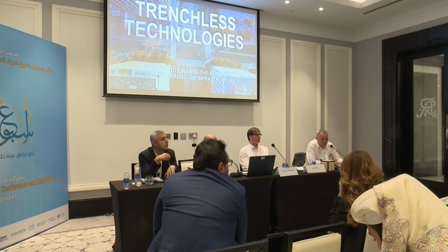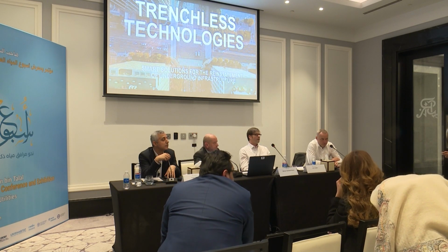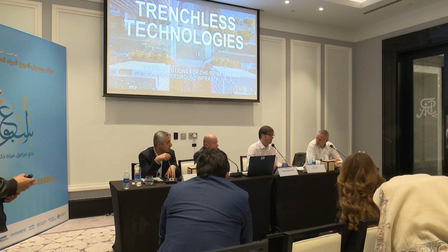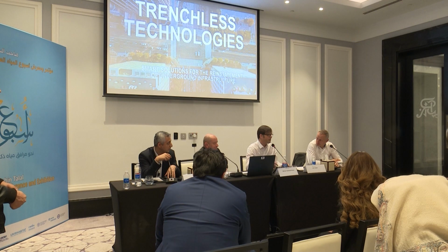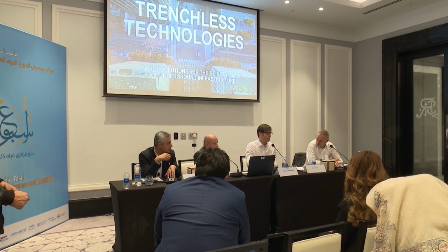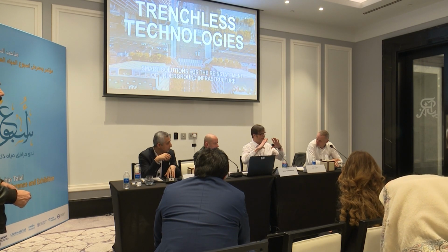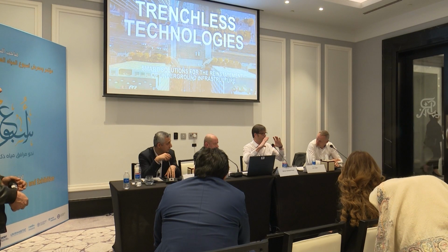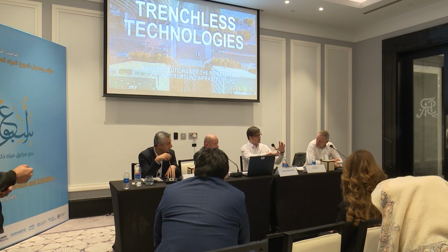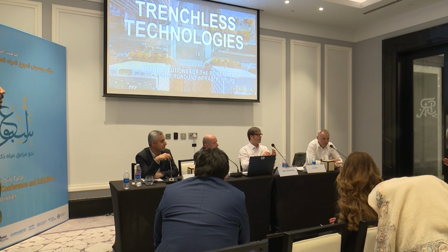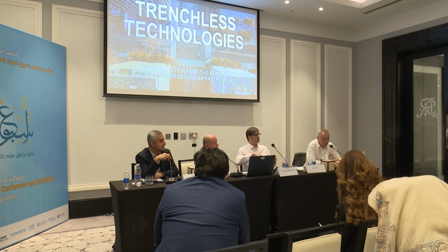So you want to enlarge even. I cannot imagine how I can enlarge. I have a specific diameter. It is impossible. It is the application of brute force. As long as you can get the bursting rods through the pipe, we can put a larger bursting head or expander, whatever you want to call it, on the other side, and it follows the path of the existing pipe. It breaks the existing pipe open, it cuts it. How can you get it out? You don't need to get it out, it stays in there. You just displace it into the surrounding soil. Yeah, it stays in the soil.